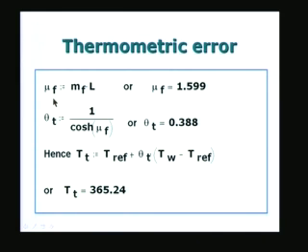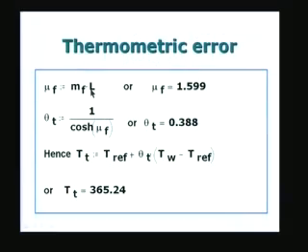And the non-dimensional governing parameter for the fin is given by the product of the fin parameter, which is calculated earlier, and the depth of immersion. So, the depth of immersion is making its appearance in this parameter, and if I put L equal to 50 millimeters, 0.05 meters, multiplied by the value which was about 31 in the previous case, I get a value of 1.599. And again it can be shown from the heat transfer calculation that the non-dimensional temperature theta T.